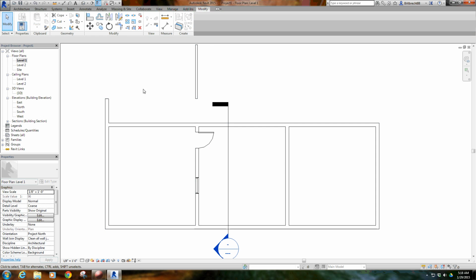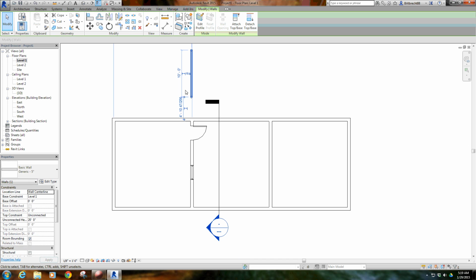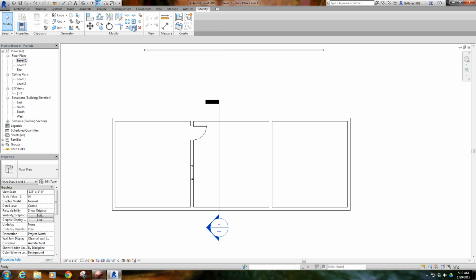Okay, so trim, it's right here. So same as in AutoCAD, except you're clicking what you want to keep. I know in AutoCAD it's kind of backwards, but I'm clicking, I want this side of it and I want this side of it, and so it cleans that joint up. If you have something like, let's take this and extend this out here, we can click this and say I want to extend to this point, and I'm going to extend these multiple things to that. It'll jump those up there.